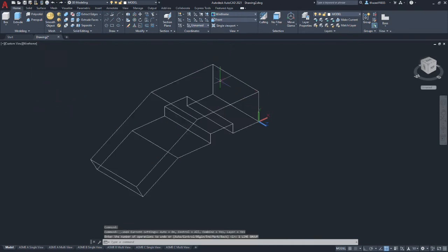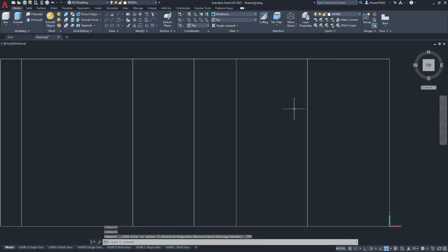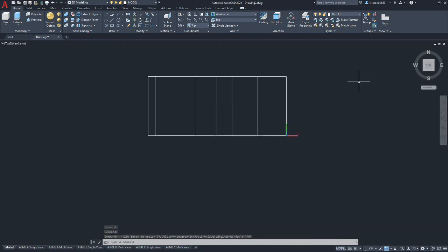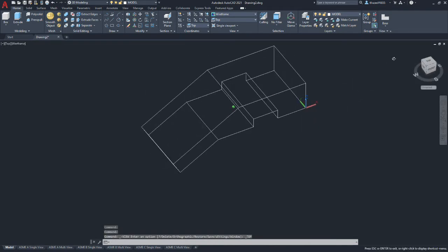Okay, we're going to draw the flange that goes on the opposite end of the part. To do so, we're going to do an extrude, and we need to change the top view. And in the top view, we'll go ahead and move back to a 3D view, but we want this set for top. We're going to draw a line from origin, and we're going to go some distance, about 5, fine. But we're going to select tab to set the angle rather than selecting another point. And that angle is 30 degrees.